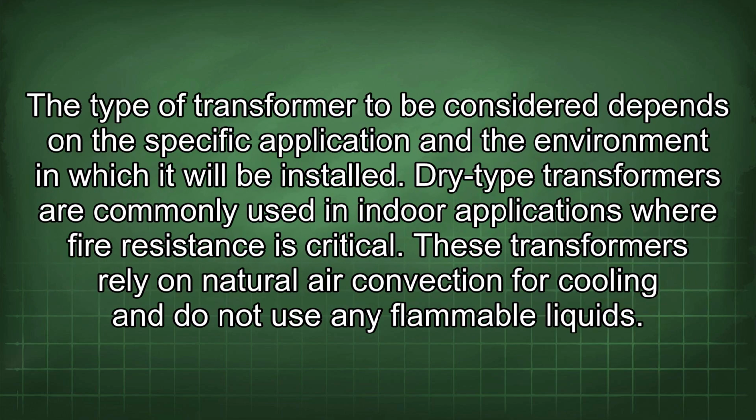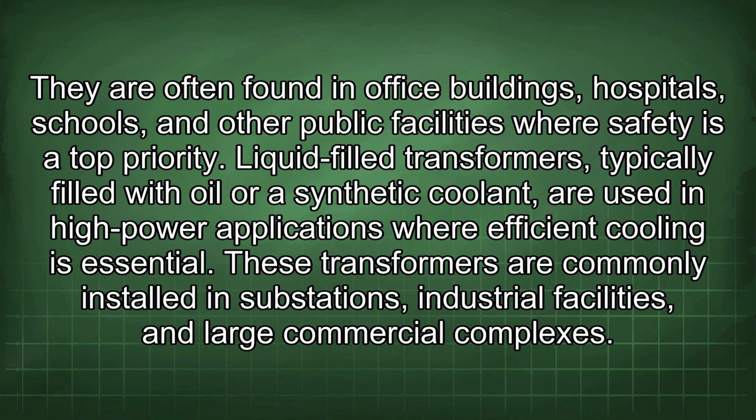The type of transformer to be considered depends on the specific application and the environment in which it will be installed. Dry-type transformers are commonly used in indoor applications where fire resistance is critical. These transformers rely on natural air convection for cooling and do not use any flammable liquids. They are often found in office buildings, hospitals, schools, and other public facilities where safety is a top priority.